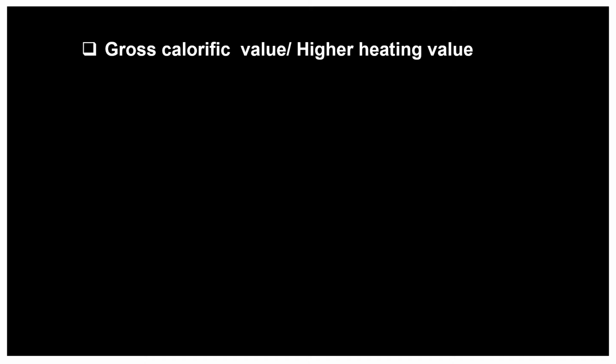So we know how much of the heat energy is utilized in converting that water to vapor. So we are adding that latent heat of vaporization or condensation also into our account of the heating value. So that is the gross calorific value.